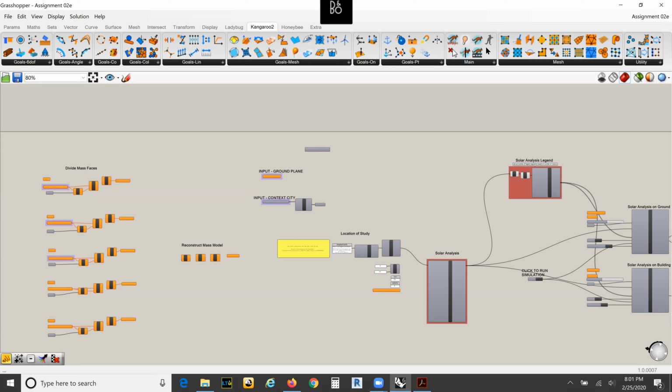Finding optimal forms through gravity is a fantastic one. That's one of the logics of how we make the fabric work: we have to apply a gravity factor to it, and that really allows us to do some unique form finding and get some very organic shapes. But they're not just shapes that look like a very cool organic shape. It's rooted in logic, and it's based on optimizing structural loads, and it's just this thin shell. So again, this is a great one.